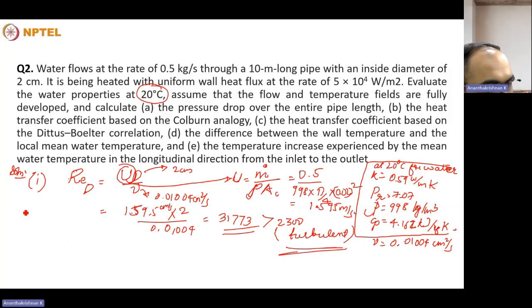So as you could see, this is the friction factor for the duct flow, and this is the Reynolds number. Initially, this is the Fanning friction factor. For the laminar section till 2300, it will follow a linear variation, given by 16 by Reynolds number.